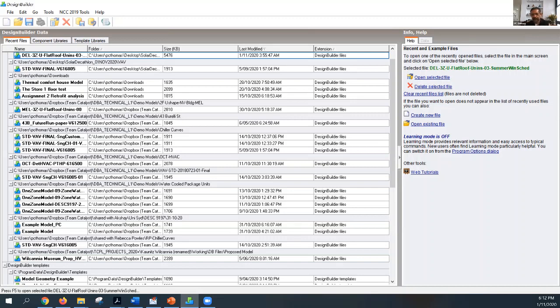Hopefully the next Solar Decathlon, we might be able to have a plugin that we can provide, which will auto calculate that. That's post-processing. You can take the ESO file, take the values that you want, and post-process that in an Excel sheet. No problem.